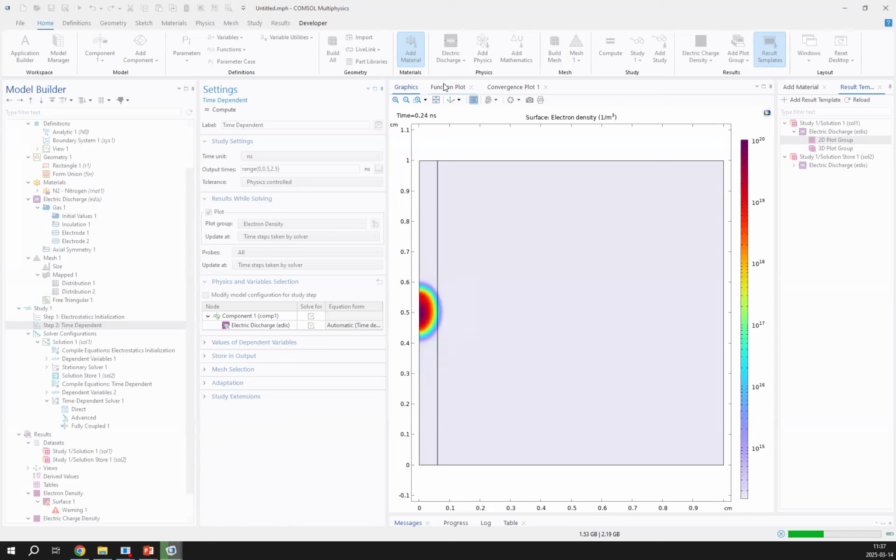of a streamer. The bottom streamer is cathode directed, and the electrons are drifting in the opposite direction of the streamer propagation. The propagation of the cathode directed streamer is only possible because it is given a high enough background electron density. For simulating a positive streamer in a weak field, the photoionization effect has to be taken into account, and the electric discharge module features such a tool.